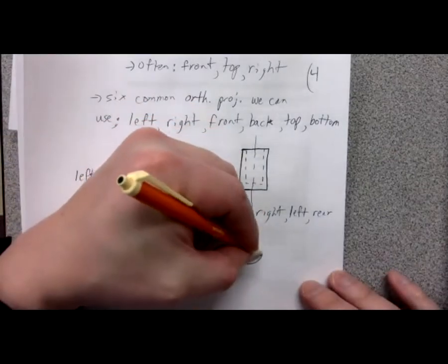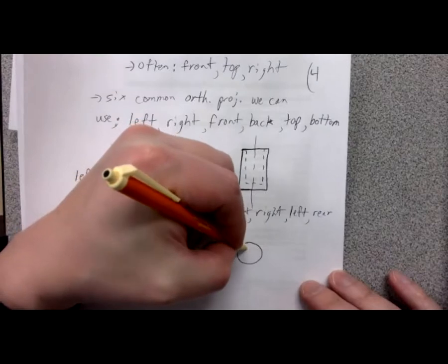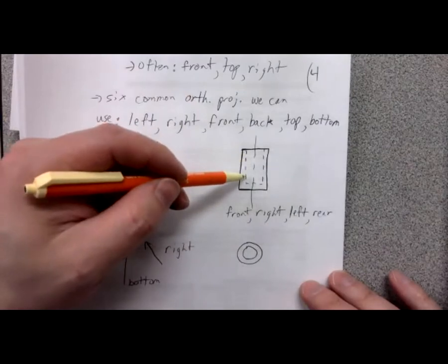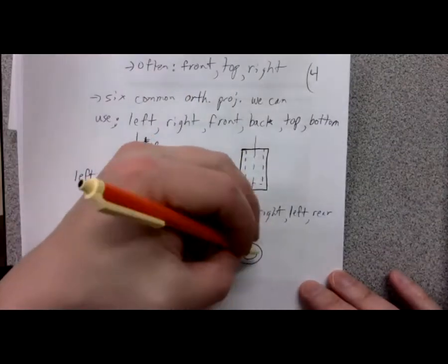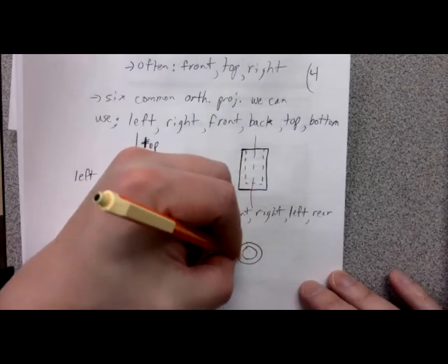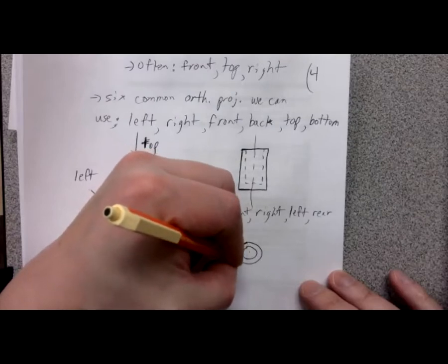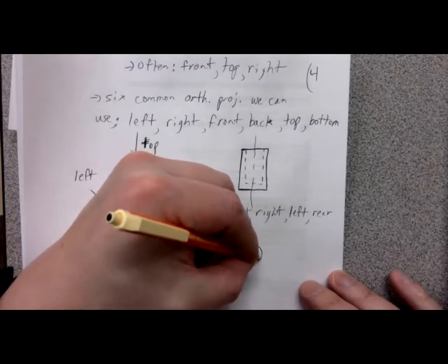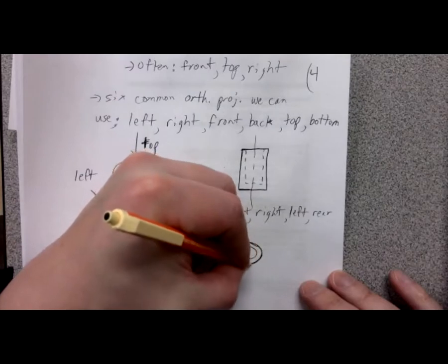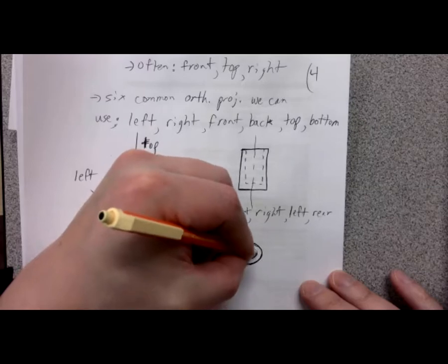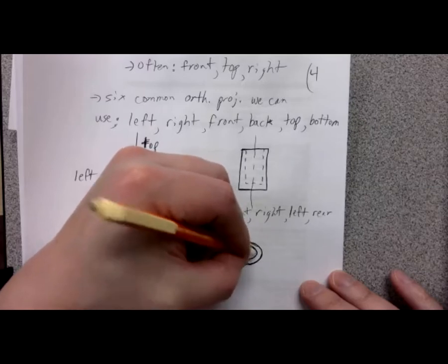If I look right straight down on this thing though, I can actually tell, because I can't tell if there's circular features from this view alone. I don't know that. But if I look right straight down on it, I will see the outer circle, the outer cylinder, and I'll see the inner cylinder removed. I'm going to make those good and solid. And if these are big circles, go in and set your center point, draw multiple points at different radii, connect the dots. Okay.